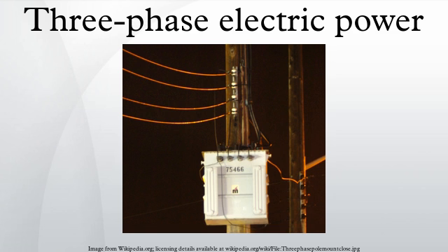The neutral allows 3 separate single-phase supplies to be provided at a constant voltage and is commonly used for supplying groups of domestic properties which are each single-phase loads. The connections are arranged so that, as far as possible in each group, equal power is drawn from each phase. Further up the supply chain in high-voltage distribution, the currents are usually well balanced and it is therefore normal to omit the neutral conductor. Three-phase supplies have properties that make them very desirable in electric power distribution systems.